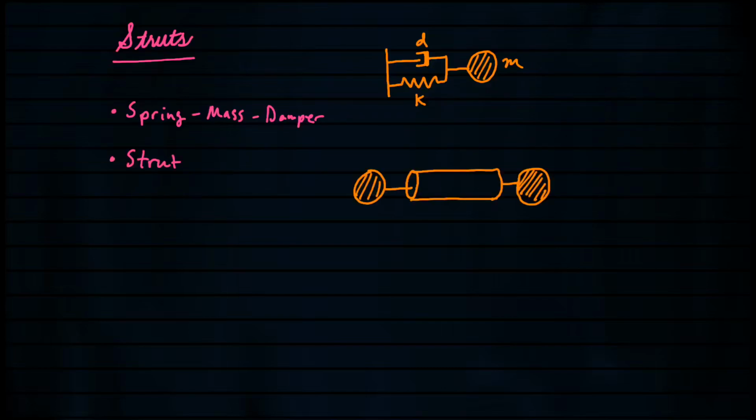And so if you could imagine two masses on one side, and we'll call mass I and mass J, and inside the middle we have the cylinder, which represents both the spring and the damper. And we have a few parameters that we're going to take a look at. So we have the spring constant that relates mass I to mass J for this particular strut, and we have the damper coefficient IJ, and then we have the length of the strut. So this kind of gives us an idea of how long is the spring, what's the normal length of the spring, and finally the direction from mass I to mass J, which is this normalized vector x, ij.